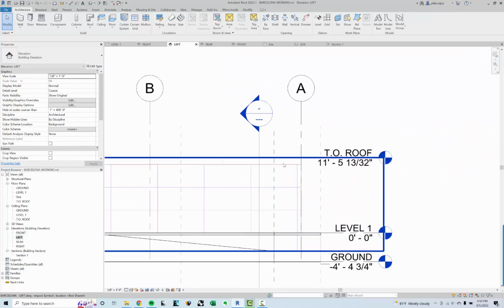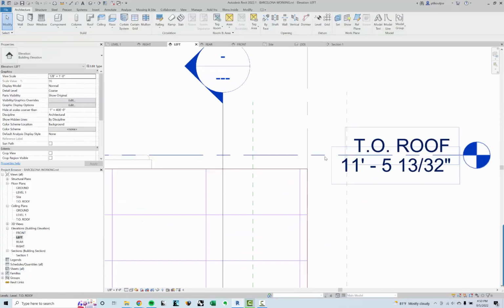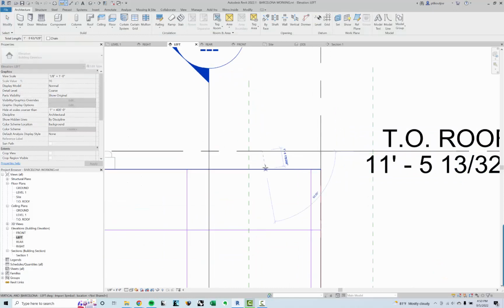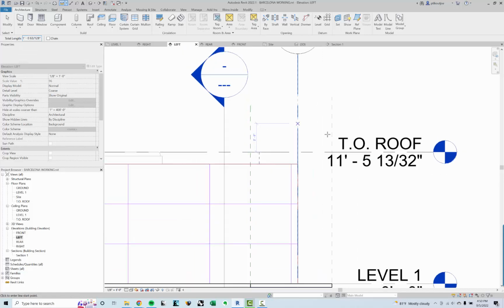But the top of that wall is actually the top of the roof minus 1 foot 63/128ths. Again, I wish the dimension was a little cleaner. That's really close to 1 1/2. Sorry, 1 foot 1/2 inch. So I'm going to use that.